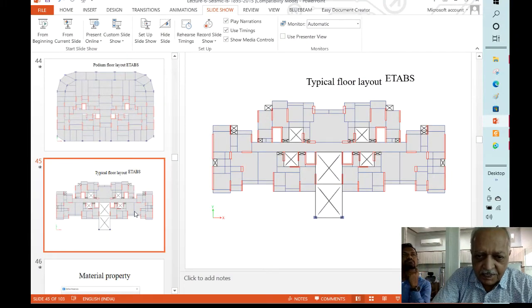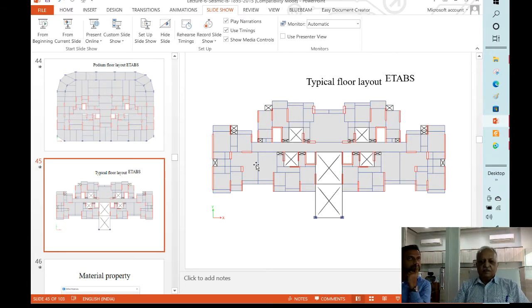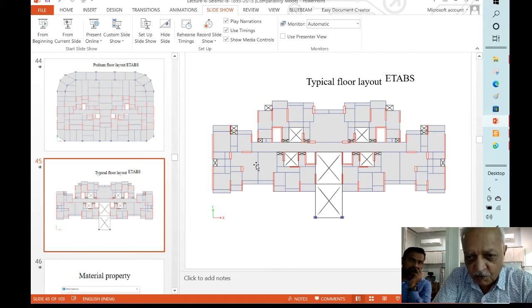So basically the initial structural scheme of things is already decided in consultation with the structural engineer and architect. You decide where you want columns, what size of columns, whether any restriction is there, and where you want to provide beams as per the room alignment arrangement and so on. So you provide the locations of the beams, the locations of the columns, and the sizes of the columns you have to decide approximately, or initially you take any size.